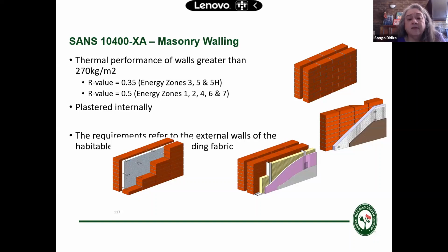What I'm saying is don't fill a cavity with brick or rubble, or, I've seen places where people use it as some kind of storage unit. It's very, very strange. It doesn't have the right effect if it's filled with a solid, non-insulating material.